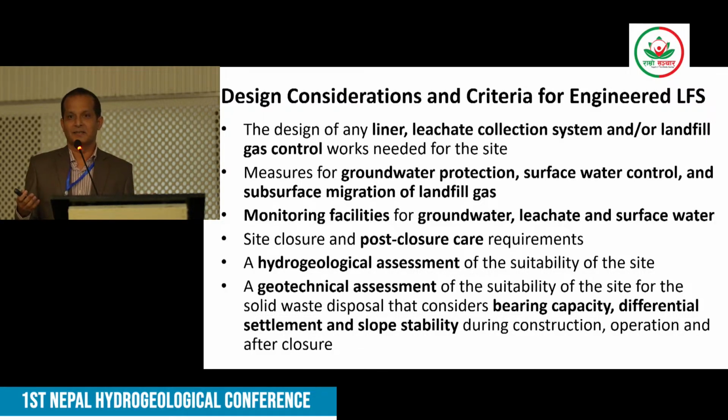And the major missing part here is that sanitary landfill, engineered landfill, whatever you say, everyone says it's like a dumping site. When you say dumping site, you don't need any hydrogeological assessment, you don't need any geological assessment, you don't need any geotechnical assessment, and you don't design any liner or barrier system. And finally, all this leachate goes to the groundwater system. And we are talking about our groundwater not being fit for drinking. This morning, our minister said the shallow groundwater is not fit for drinking. This is the reason. But we are not talking about these things.